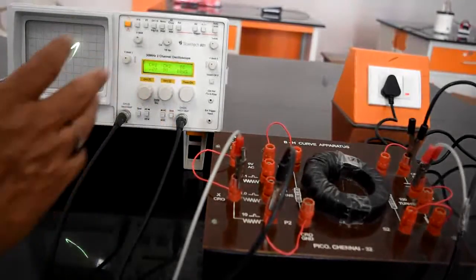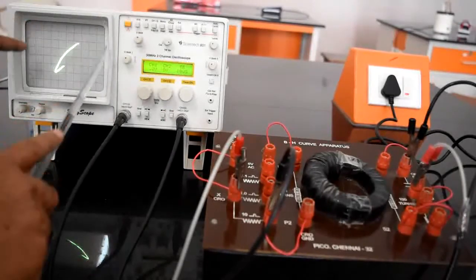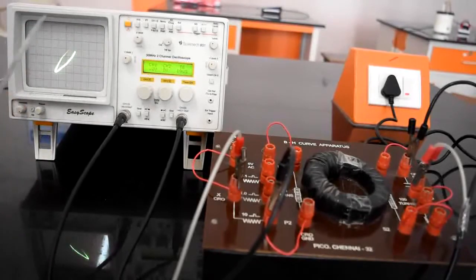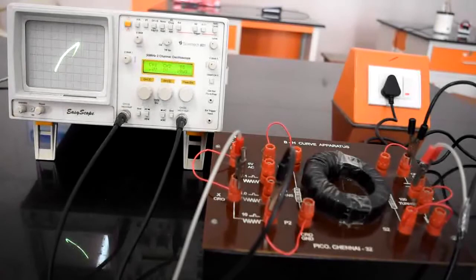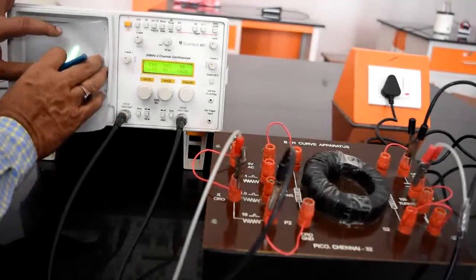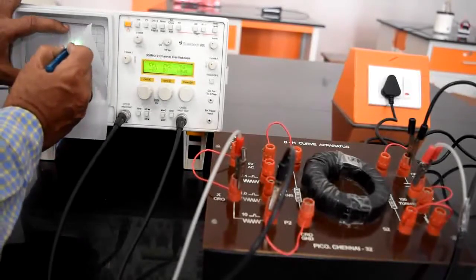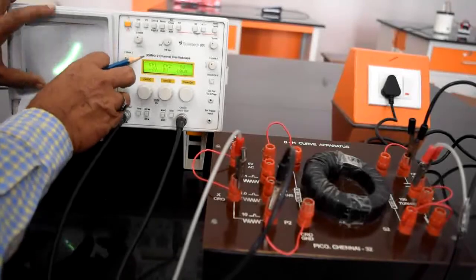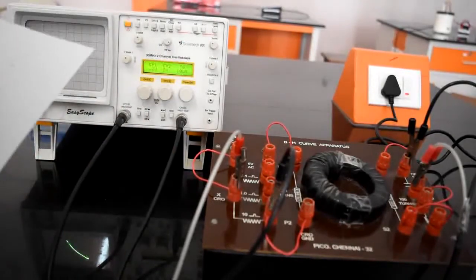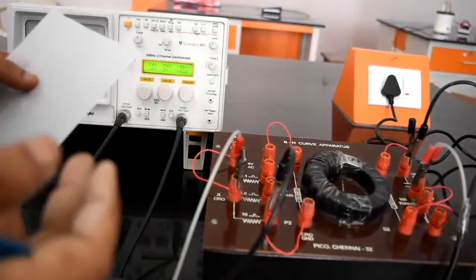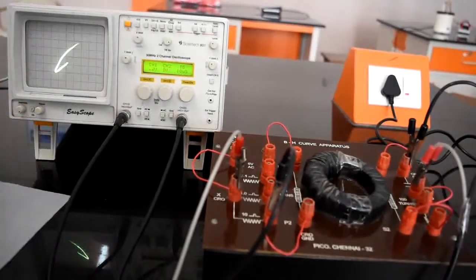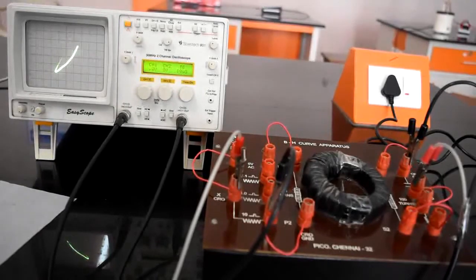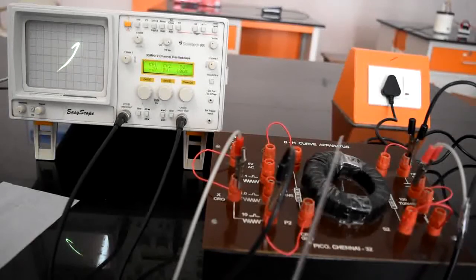So now you have Lx, Ly, everything. Now you can use a trace paper, put the trace paper on this and copy the curve onto the trace paper. This trace paper is placed on the graph paper. We keep the trace paper like this and copy the curve like this, making the center point, this horizontal and this vertical. This curve is placed on the graph paper and the number of small squares is calculated. That value gives the area of the loop, and the volume is given. Substituting all the values, we will get the hysteresis loss of the ferromagnetic material used in this coil. Thank you.